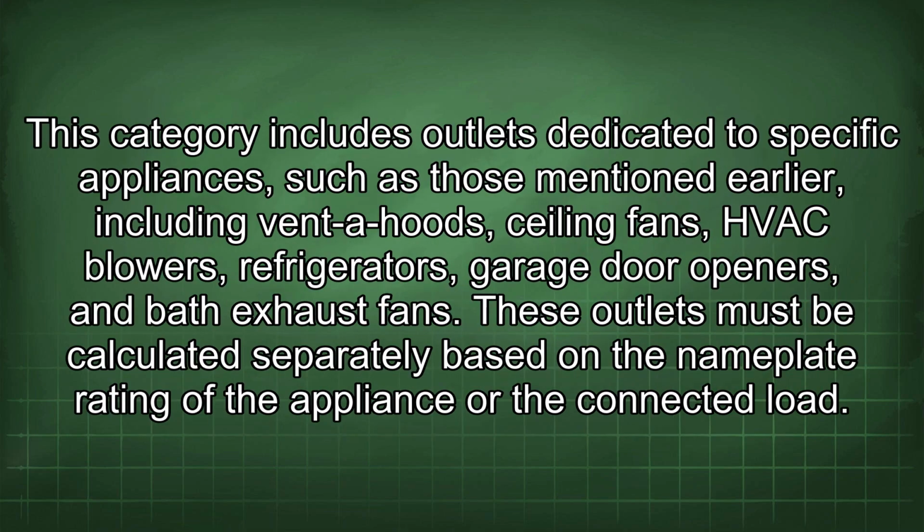This category includes outlets dedicated to specific appliances, such as those mentioned earlier, including vent hoods, ceiling fans, HVAC blowers, refrigerators, garage door openers, and bath exhaust fans. These outlets must be calculated separately based on the nameplate rating of the appliance or the connected load.